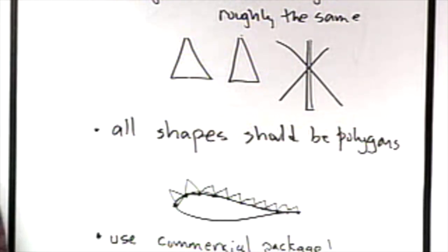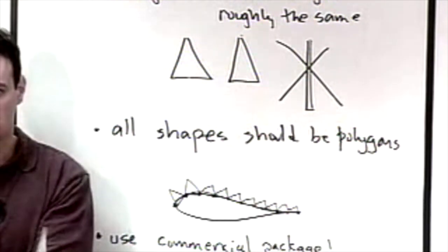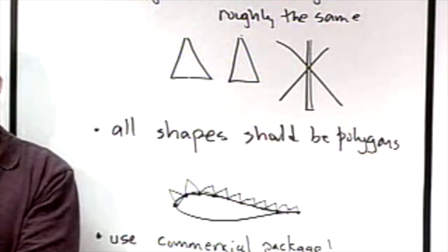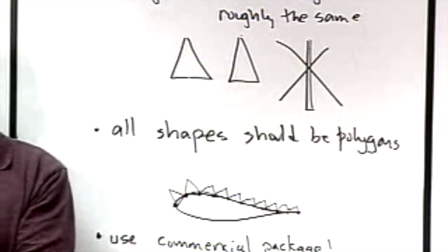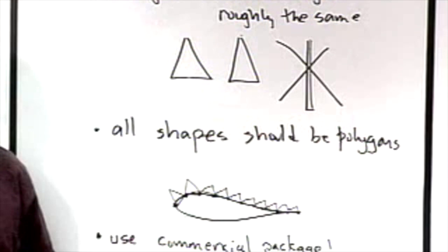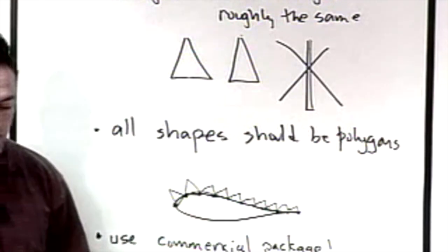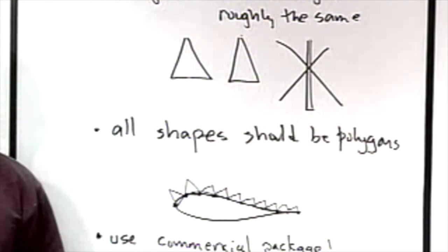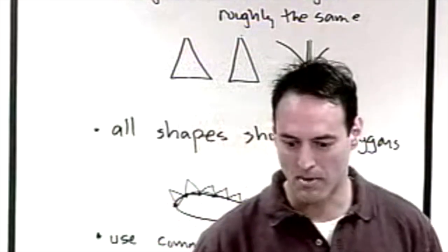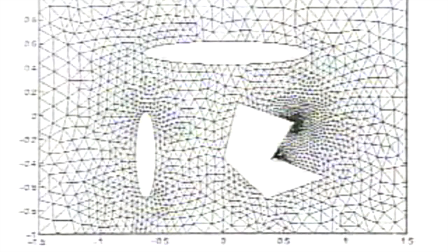There's also ANSYS. ANSYS, is that used in your department, right? A bunch of people there. So, pick your poison. Each one of them has its strengths and weaknesses, but for the most part, they're going to get this part right. This is pretty standard stuff. Discretize your domain. You're going to somehow specify your boundary conditions, everything like that. You give your domain shapes, and boom, you just say, give me the grid, and it's going to give you something like this.